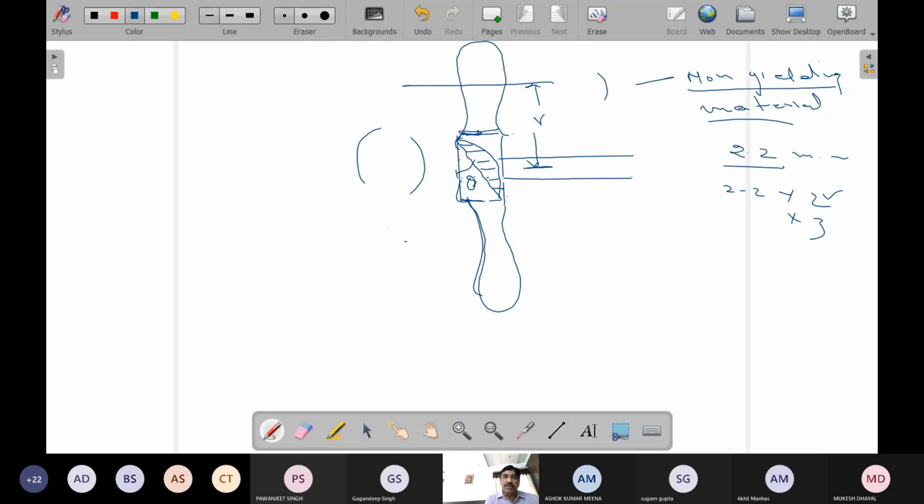then when I rotate this section through one complete revolution, it will move forward. Now that means that in this plane, the distance traveled is 2 pi r of this section, because it is at a distance r. So this section will travel a distance equal to 2 pi r, the perimeter. I am just taking a line from the center line and calling it 2 pi r, and forward it will move equal to the pitch, and the angle over here is theta, although we are trying to make it similar, but there may be small differences.